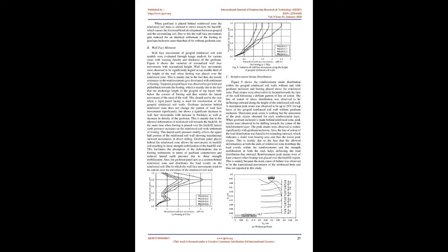During the construction of the reinforced soil, a wooden formwork was placed at the rightmost corner of the strong box. The wooden formwork ensures the aligned construction of the reinforced soil wall at 90 degrees to the horizontal and avoids any deformations during the construction process. 4 permanent markers were glued to the glass panel so as to provide a benchmark to measure movements of the geogrid markers during the progress of the tests.